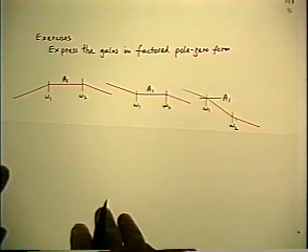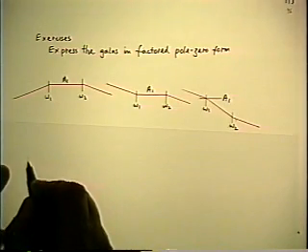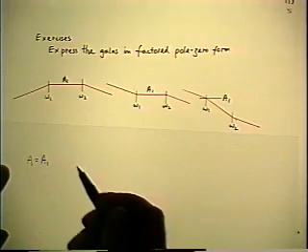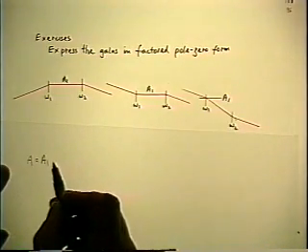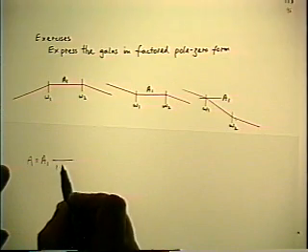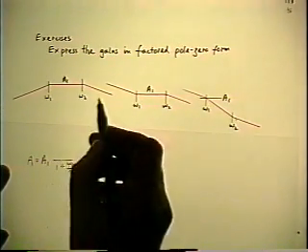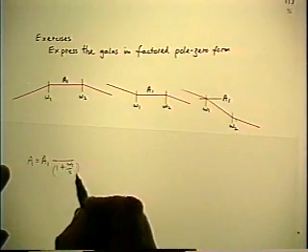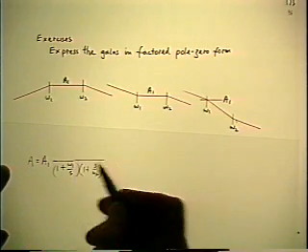Let's look at the first one. One flat gain, take that as reference, A equals A1, look up and down in frequency. If you look down in frequency, there's a concave downwards corner, so that's an inverted pole at omega 1. Look up in frequency, concave downwards corner, that's a normal pole, 1 plus s over omega 2, no zeros.